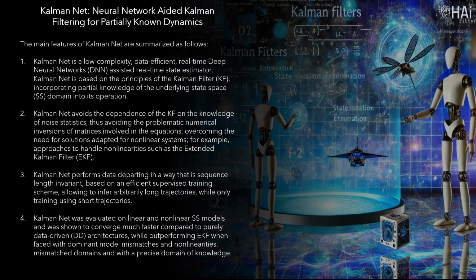KalmanNet avoids the dependence of the KF on the knowledge of noise statistics, thus avoiding the problematic numerical inversions of matrices involved in the equations, overcoming the need for solutions adapted for nonlinear systems, for example, approaches to handle nonlinearities such as the extended Kalman Filter, EKF.